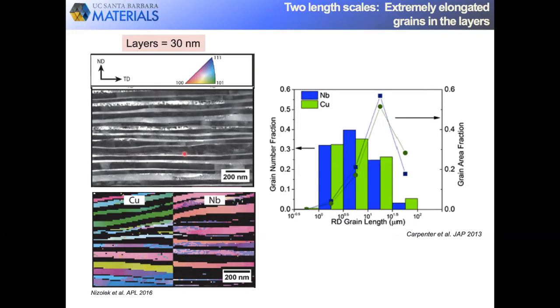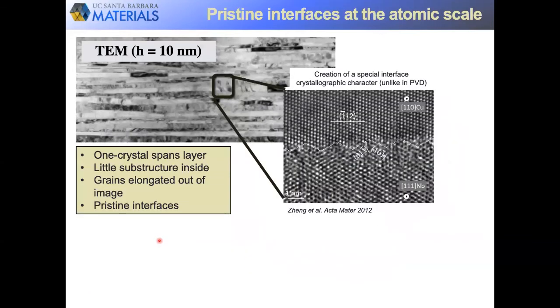In these ARB nanolayer materials, they were nearly 80 to 100 aspect ratio. So essentially, and also as we can visibly see here, these layers are single crystal sheets. And another way to look at it is that there are fewer grain boundaries than there are bimetal interfaces. So truly bimetal interface dominant, few grain boundaries.